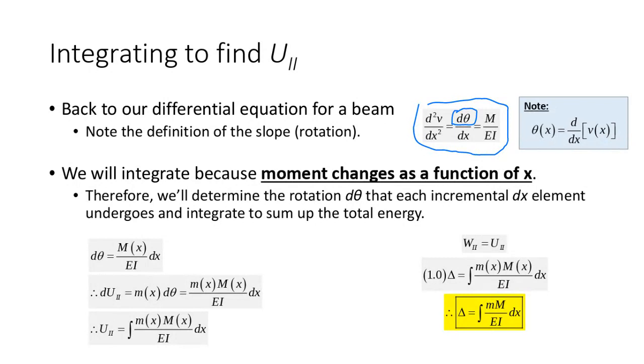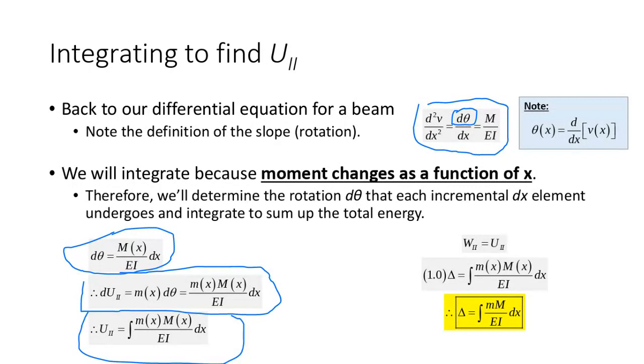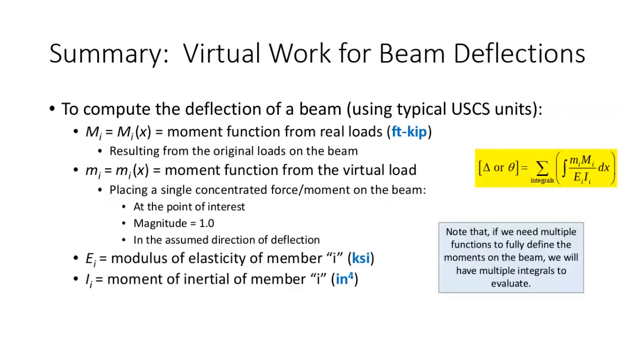It's just M over EI dx. I'm taking that, rearranging it, and solving it for d theta. So if I have that, I can write out my little incremental energy component right here and sum it up. Sum that up, and boom, there's your displacement.